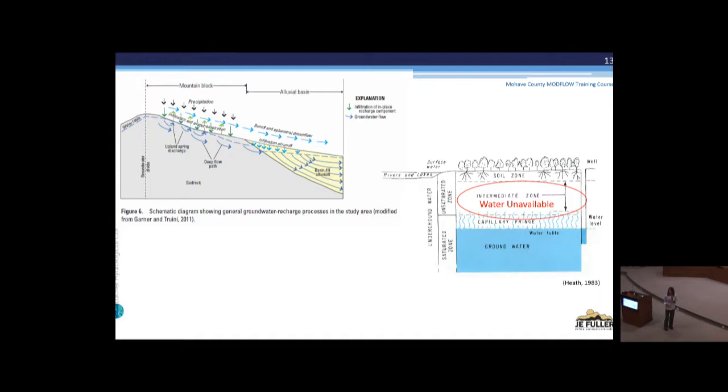It will eventually, gradually drain by gravity into the groundwater system, but just because you recharge water through the root zone, for example, doesn't mean you're going to be able to access that water again, unless you manage to overcome this unsaturated condition and wet up the whole thing, and then begin to get saturated flow, which is much more rapid. So importantly, if you start a recharge project, you need to account for the time it's going to take to wet up and build a mound up closer to the surface so that you can actively recharge and then expect to be able to access that water later in time if you want to. But it's not an immediate process.